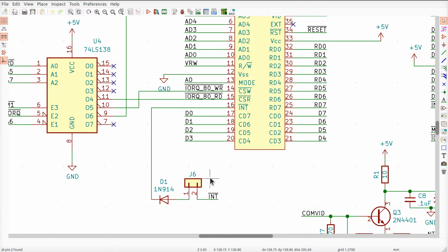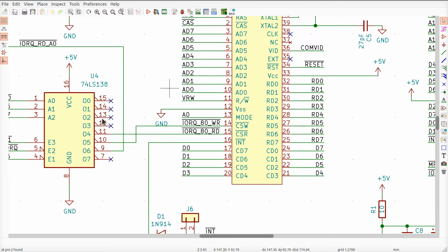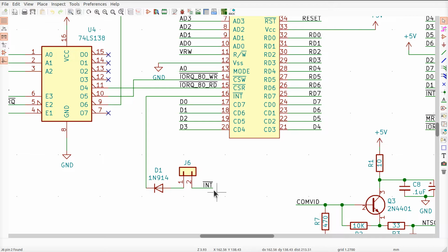Now, I also put a jumper in here because we may not want this connected in any way, shape, or form. And that may happen if we can't really get the software to work right. I haven't done a lot of interrupt tinkering yet with the Z80 Retro, but the I/O ports and stuff that are on the retro board itself, the CTC and the SIO, are configured to run in what we call mode 2. And this thing doesn't know how to speak Z80 interrupts. So if I connect this up directly to the interrupt bus, we're only going to be able to generate mode 0 interrupts. We'll talk more about that later when we start messing with the code.